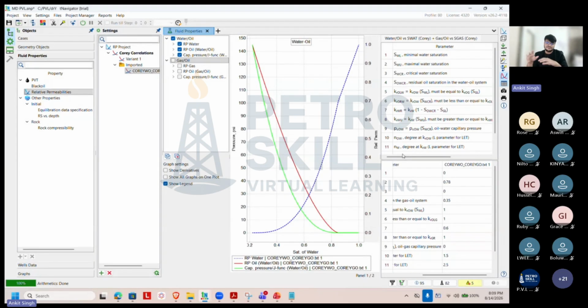So with tNav, you have covered most of the important things, and it is going to be very useful for you when you go and work, as you have first-hand experience of how reservoir simulation works. Currently, you will just learn button clicking, but once you observe the reservoir behavior over time, you will see that relative permeability and PVT are the most important factors in reservoir simulation.